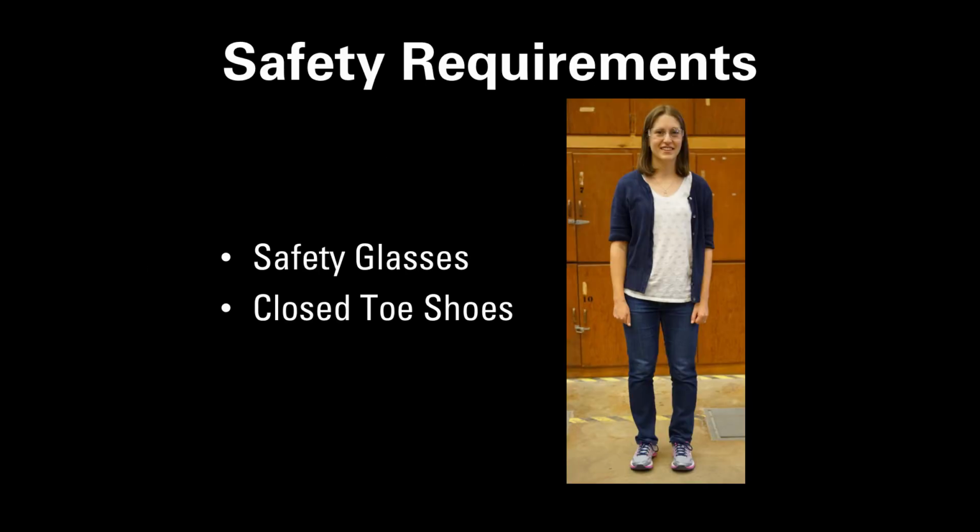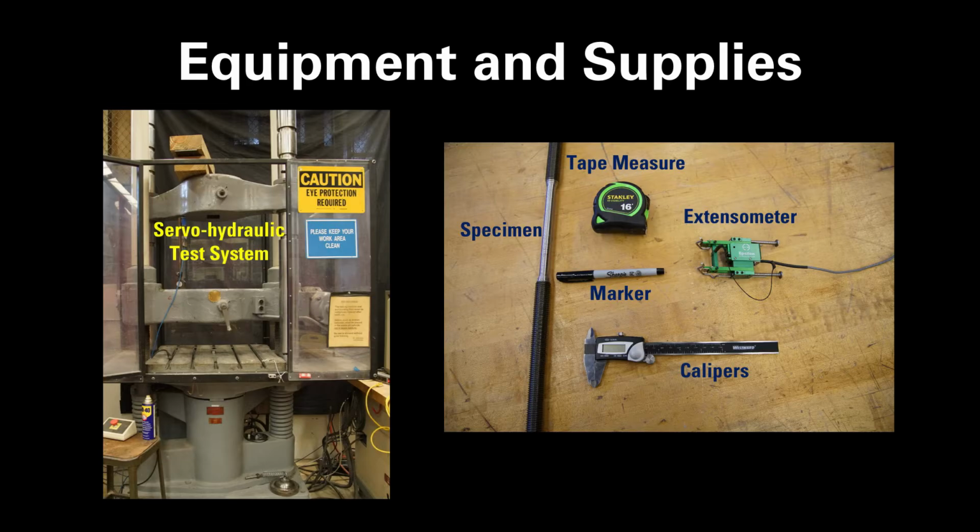When performing tension tests, the following safety precautions are required: safety glasses and closed-toe shoes. Also, please note that a loud noise upon failure of the specimen is expected. The following equipment and supplies are required for conducting tension tests: a servohydraulic test system, a test specimen, a tape measure, calipers, a marker, and an extensometer.